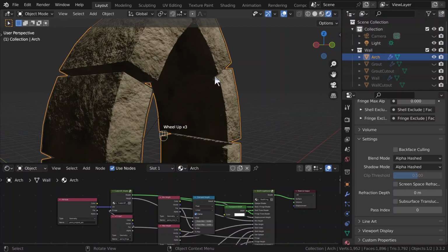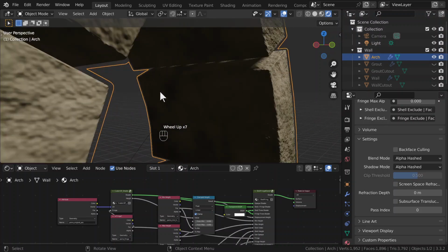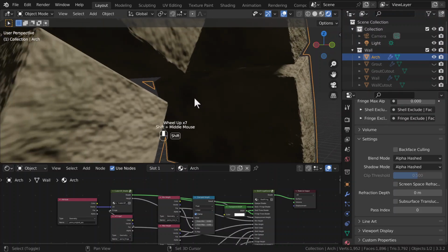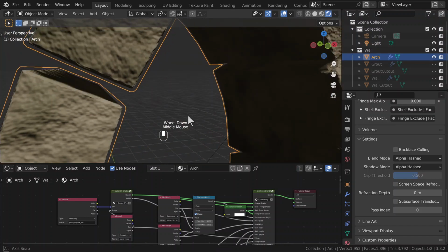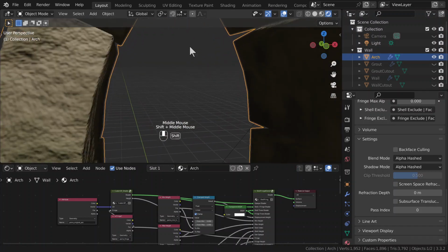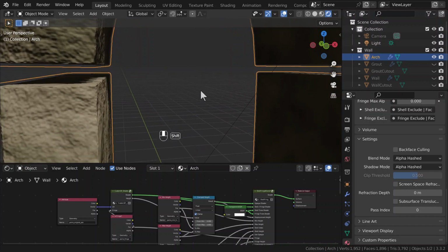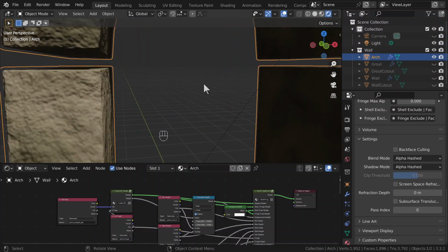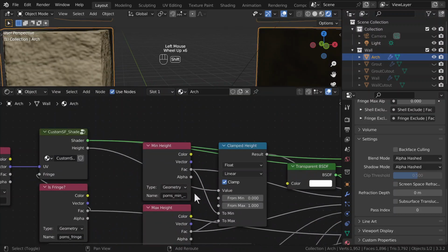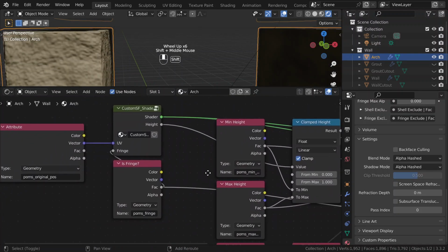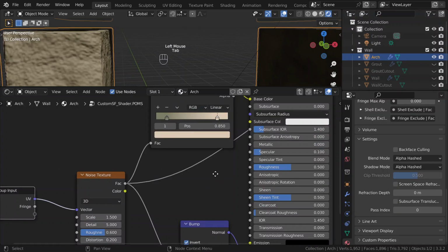There. Now the effect is visible, but the effect is subtle and there needs to be an increase in the number of layers or shells. The orange outline kind of gives it away that there's some depth to this now. To increase the height contrast, I'll click on the green node that has our custom texture and press Tab to edit the node group.